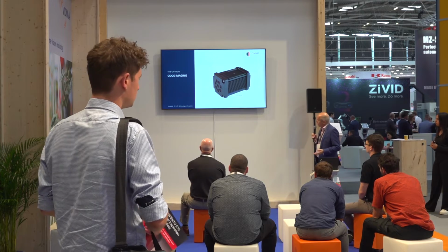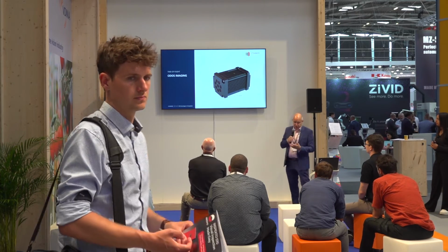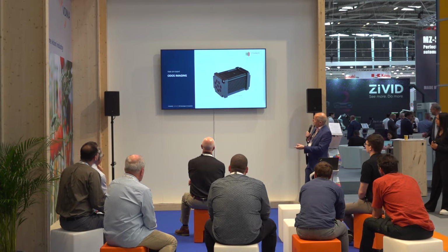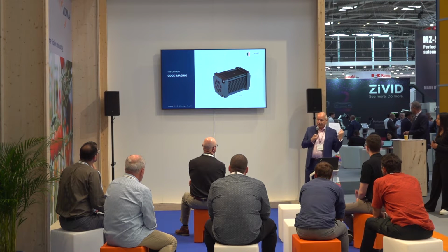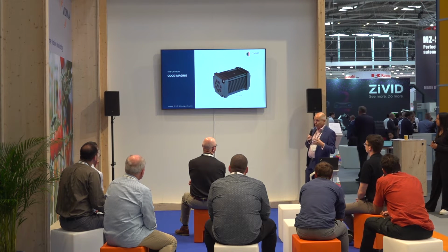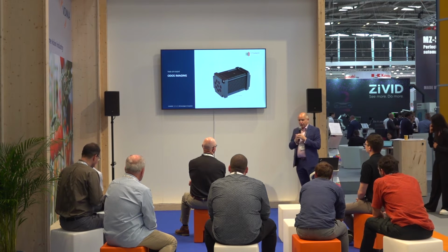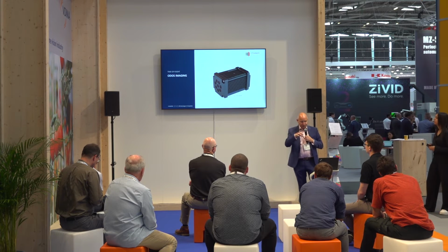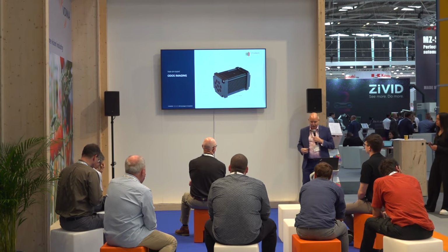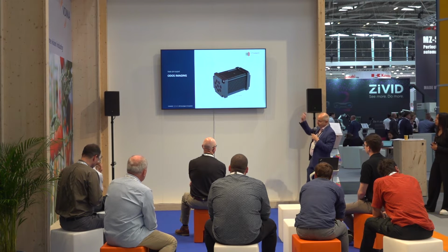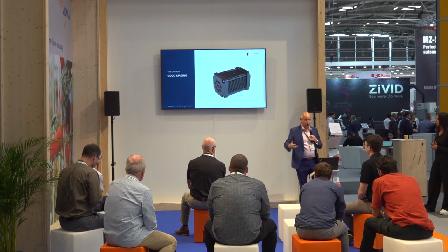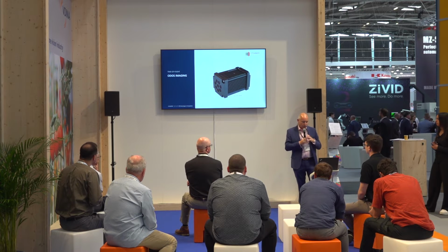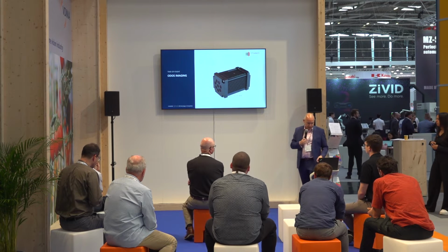Product we work with from Odos, which is a part of Rockwell Automation. They do one of these devices, connects with GigE directly to a vision system, or you can get a smart version where with a web browser you can draw boxes and measure heights. So for instance, I did that bottle application, you can do that connecting directly with Ethernet IP to your PLC. No other software, no other box required. So quite easy, IP rated and good.